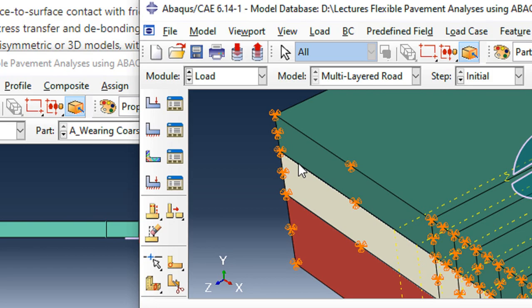So it considers the material heterogeneity and load transfer mechanism. And if you remember in the previous video, I discussed the modeling of the pavements, in which I did a demonstration of LET theory. So keeping in mind those points, material heterogeneity and load transfer mechanism can be handled in ABAQUS with careful attention to the pavement soil interaction and the interlayer interaction in between these parts here.